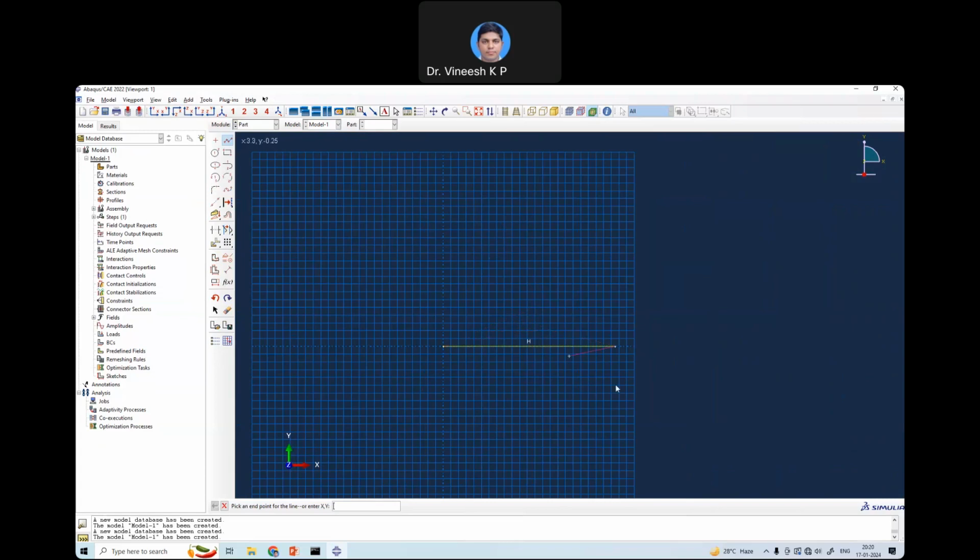So you can see Abaqus has created a line of length 4.5 meter. Remember that Abaqus doesn't have an inbuilt unit. I am assuming all the values which I am going to enter are in SI units, so the length is also in SI unit. So now I got a line of 4.5 meter length. Then after that, I don't need the second line, so I will just escape it. When you right click on the mouse, you will have a cancel procedure option. You will just cancel the second segment of the line.